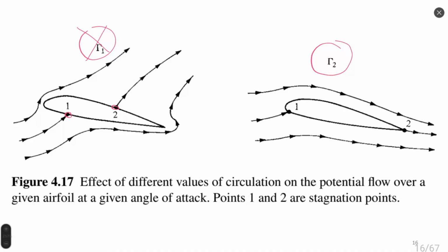also we can find numerical solution case 2, depending which boundary conditions we set. We can find case 1 and case 2. Case 1 not possible. Case 2 is the real flow. In case 2, second stagnation point is placed exactly on the trailing edge of our airfoil. So Kutta condition allows us to obtain, solving numerically, stagnation point at the trailing edge of the airfoil.